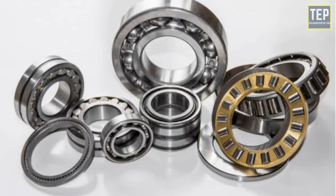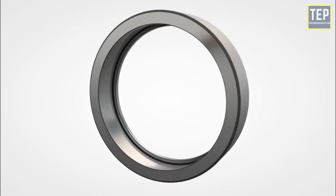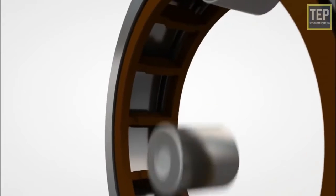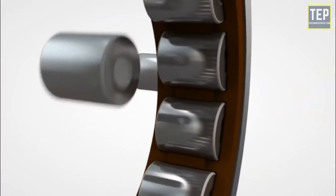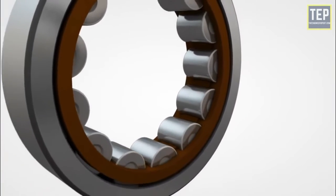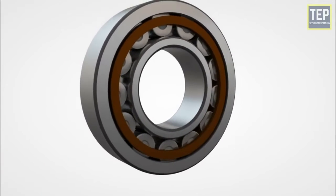In roller bearings, there are also various types, such as cylindrical roller bearings, which use line contact between the rolling elements and the raceways, which optimizes the distribution of stress at the point of contact. These cylindrical roller bearings have a very high radial load rating. Depending on the design, they may also be able to transmit limited amounts of axial loads.